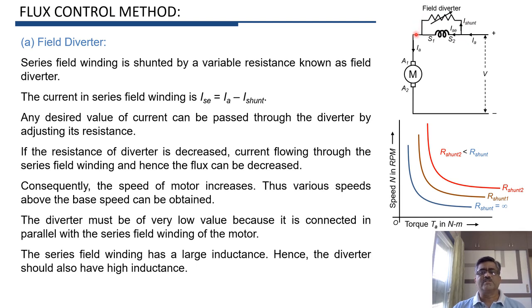So to avoid this, this field diverter must have high inductance, which is comparable with the inductance of this series field winding. Then only the operation will be satisfactory.